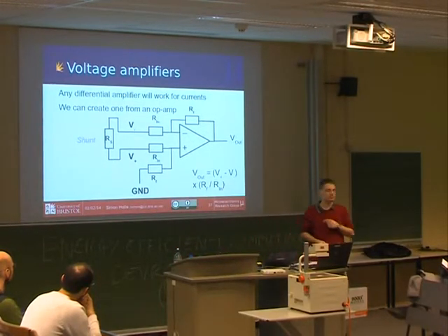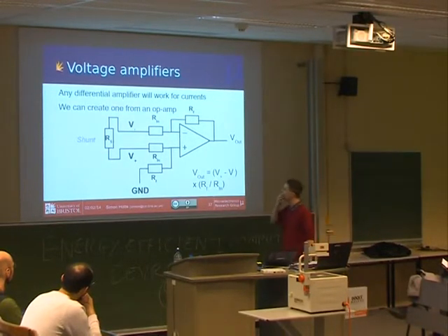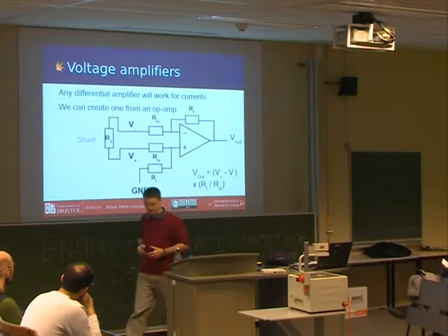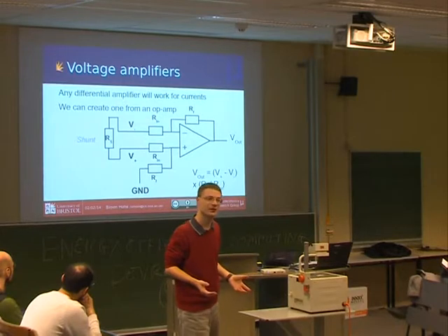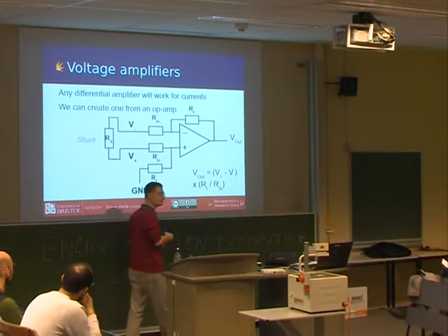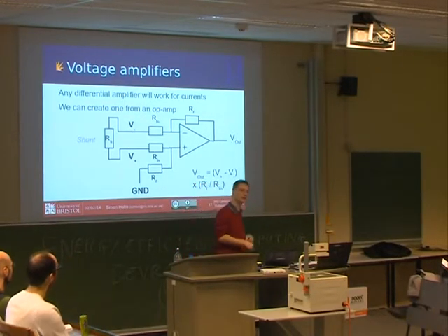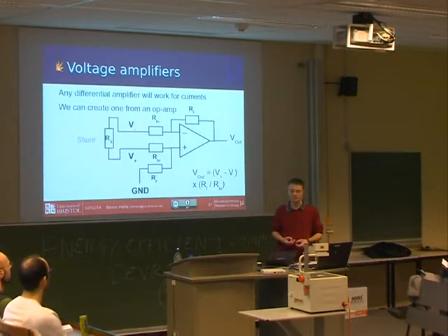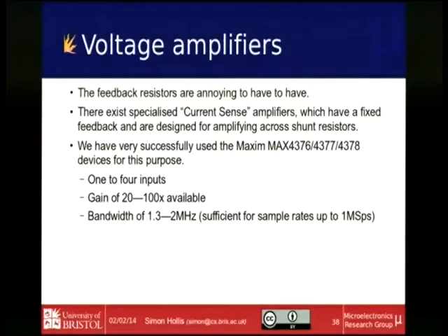The downside to this is, when I started thinking about building this circuit since we make boards based on it, you find out weird things. Like the fact that having 4 resistors here adds more cost to the assembly of your measurement board than it does to buy the operational amplifier. That's because the robot now has to go to 4 more places to place 4 more resistors, and we've got 2 different values, so there's an actual cost to making this. If you wanted to mass produce this, it's a much less attractive way forward. It's also annoying, breaks your layout, and doesn't look so pretty.